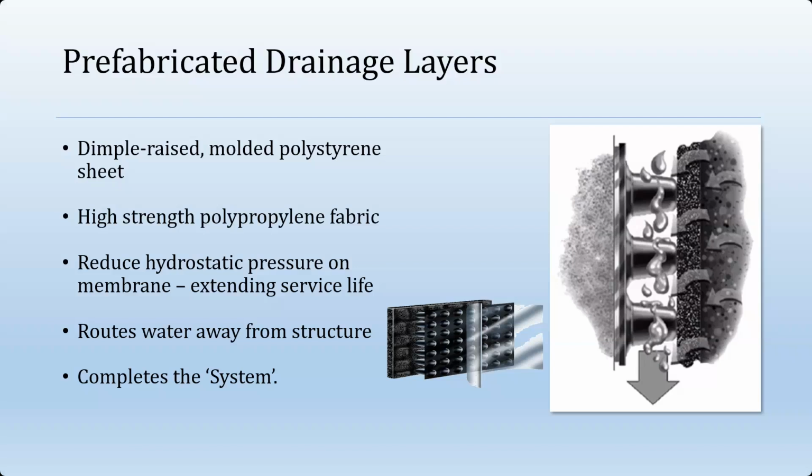If we place the drainage mat on the outboard side of the insulation, it places it in closer proximity to the atmosphere. And like, I'm dating myself here, but the big old tin cans of 32-ounce Hi-C punch, or in fact, 70 years ago when beer was sold in cans where you had to use a can opener, you'd have to actually pierce both sides of the top of the can, opposite sides. So as you poured the liquid out, air would go in and displace the liquid that was going out. It's going to provide more efficient drainage.